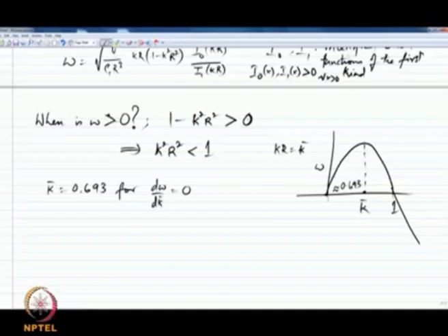fastest. And again, one of those remarkable coincidences of linear instability analysis when compared to experimental observations, that this particular wavelength has been observed in very simple faucet breakup, liquid jet breakup experiments, let us say from a bathroom faucet.